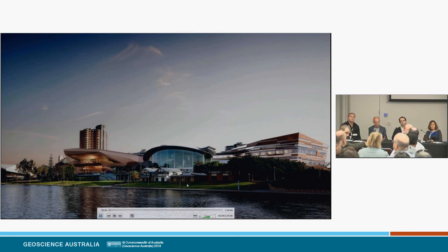I'd like to make a point about the digital terrain models or LiDAR sources. When LiDAR is processed, they're taking first returns and last returns, which will often represent the top of the canopy versus the top of your soil surface or ground surface. And I think us as an industry, we should push for both of those surfaces because it's collected at the highest resolution, and we can use the top of the canopy and the top of the soil or ground surface, both of those, to improve our products, rather than just rely on a lower resolution product to represent our canopy top.